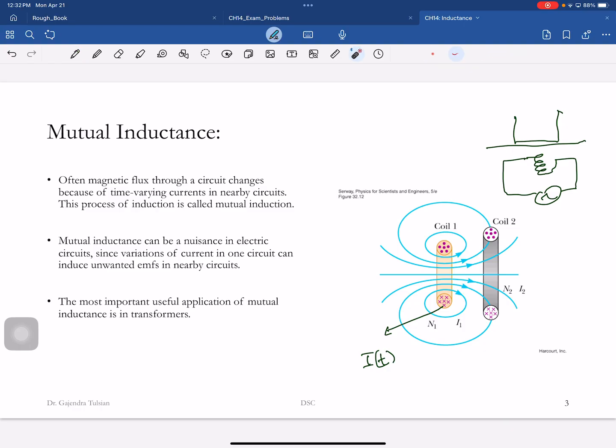What's happening is this AC source is changing the current direction 60 times a second. So the magnetic field here is changing 60 times a second, and that induces a current in this pot, which heats up the pot. Okay, so that's how the inductive coil works. It's not heating this glass top, it's directly heating this pot.